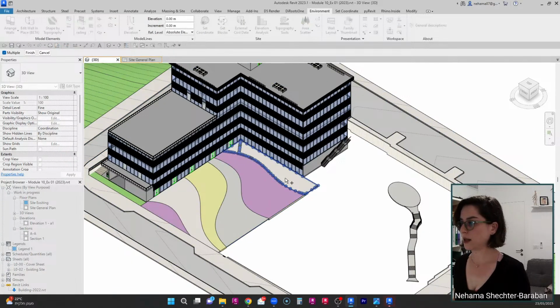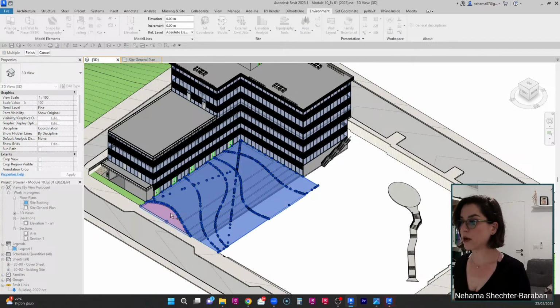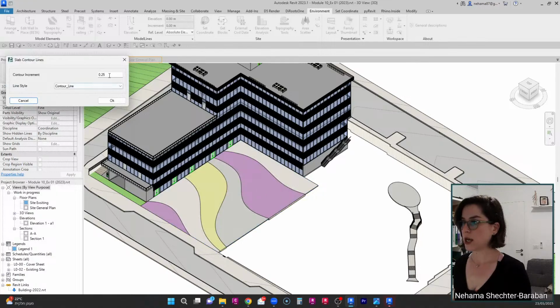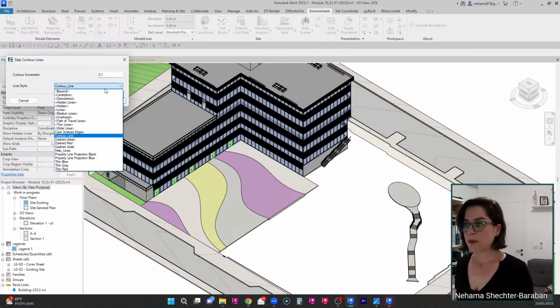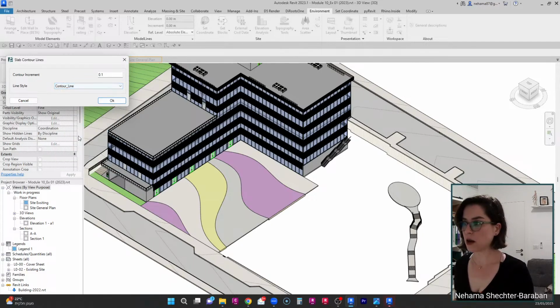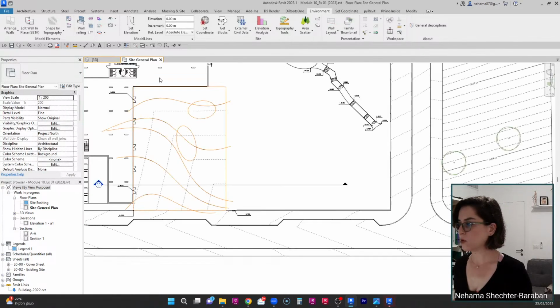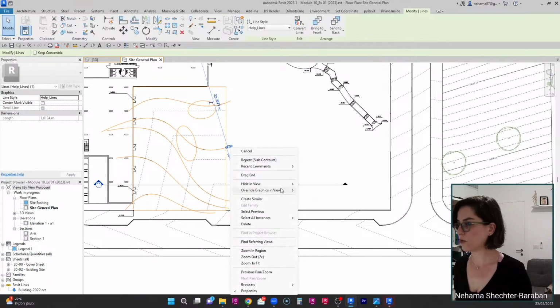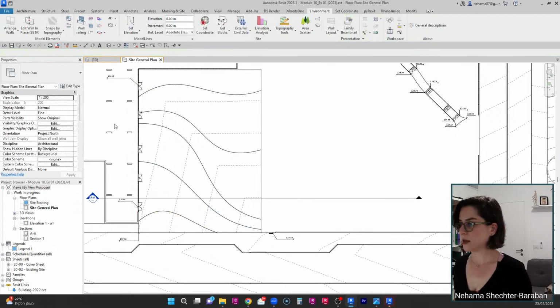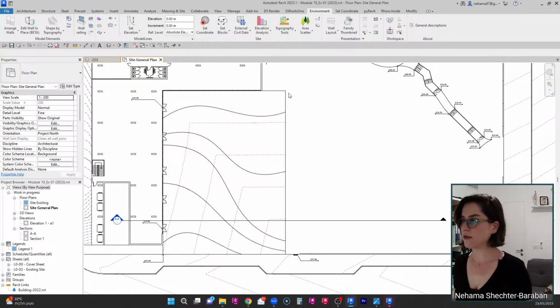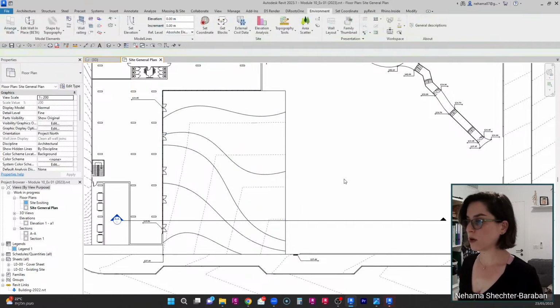Clicking on that allows me to select both floors and roofs. Click on finish. And now I can place contour lines, let's say every 10 centimeters. But these contour lines would actually be made of model lines. So I can choose any model line style that I have in my file. Let's select this contour line style and click on OK. And let's move to plan view, turn off these lines, and you can right away see that even using floors, I can get very good documentation.